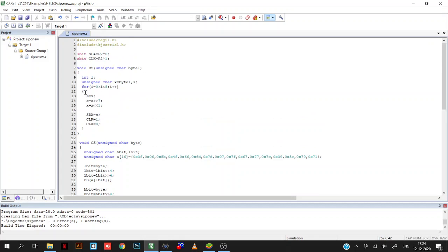So let's see, here in my first function what I will be doing is I'll be collecting my byte. Here I have declared integers i and x, and character as x. Whatever byte I will be taking will be stored in my x. Then I will do the shifting procedure. So when I enter 01, it should go to the proper position. Since I am giving the loop for 8, I will be shifting it 7 times, and then left shifting and right shifting will be done accordingly.